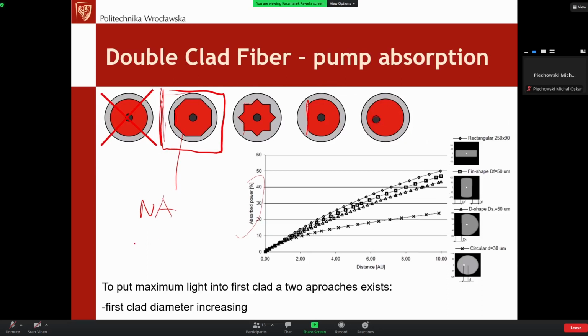You remember, if the light is propagating in the fiber, some small part of this light is also propagating in the cladding. So if you have a polymer as a cladding, you need to have a cladding with quite good optical quality, just to avoid losses and attenuation of such a signal, especially if you think about high power. If you are transmitting extremely high power, 600 watts for such a fiber, the polymer needs to be extremely pure, just to avoid any heating up or even burning of such a cladding.